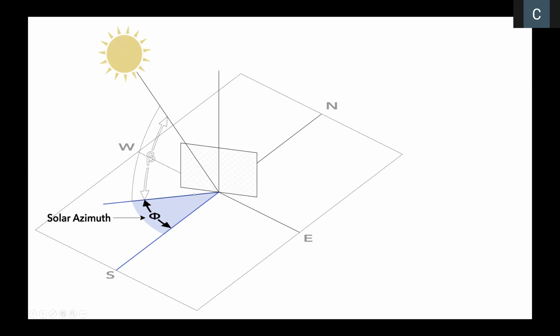And the solar azimuth, which is taken, if you were to draw a line straight due south from whatever point you are trying to measure the azimuth for, then you draw a line straight south, and you draw another line also in plan, which is to say on the surface of the Earth, and it is the projected line of this Earth-Sun ray. If you were to just drop it straight down to the ground, then you measure that solar azimuth from south, always starting from south, to that projected Earth-Sun ray in the plan view.